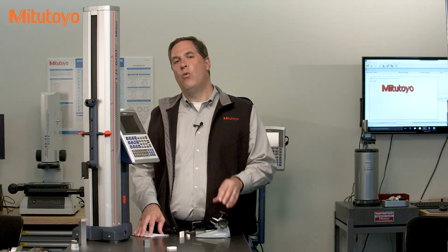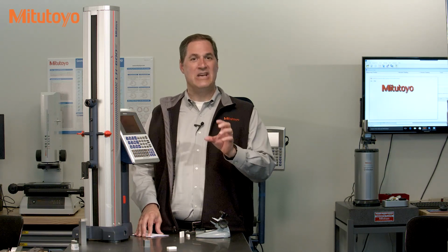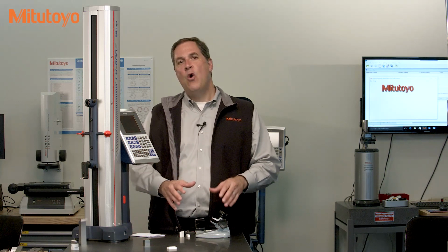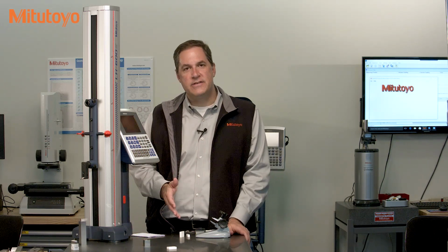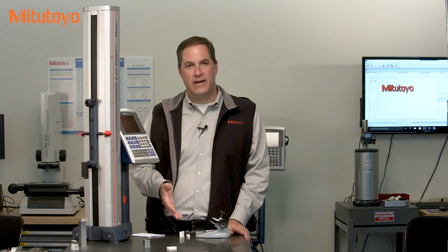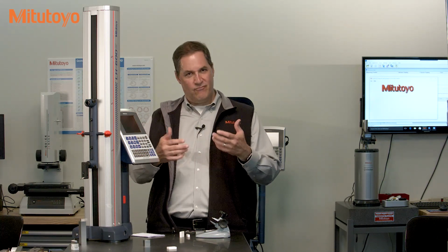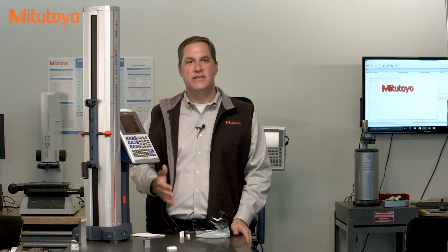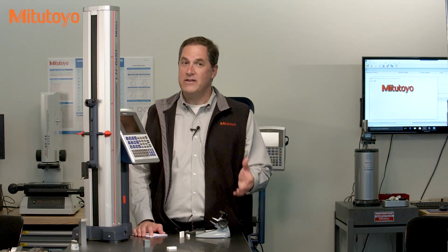However, it happens. And the worst case I've ever seen, in my experience, is where the TUR was 0.1. In other words, the calibration was 10 times worse than the equipment being calibrated. Really? That's like giving a toddler a pair of scissors and asking them to give you a haircut. It's not going to turn out well.